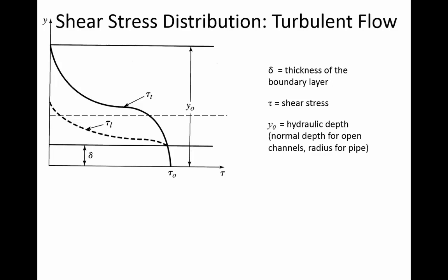when the velocity is high. So in other words, if we look at the cross-section here on the screen, if the water is moving slowly, then maybe the shear stress is pretty high in this shaded region, but on the inside there's not much shear stress, and so the water is moving without too much resistance when the velocity is low. When the velocity is low, the shear stress isn't reaching out into the flow field as much. And that's part of the reason why in a low velocity we don't have very much head loss.